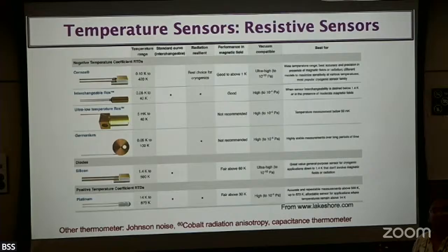That was my dream, and it didn't work out very well because of this kind of crystal that I showed you. The plan was to apply aluminum, then aluminum oxide, an aluminum junction, and then measure the junction's Johnson noise. I just cannot deposit aluminum film on top of this crappy crystal. Even though it looks very shiny and beautiful, aluminum just didn't like it.